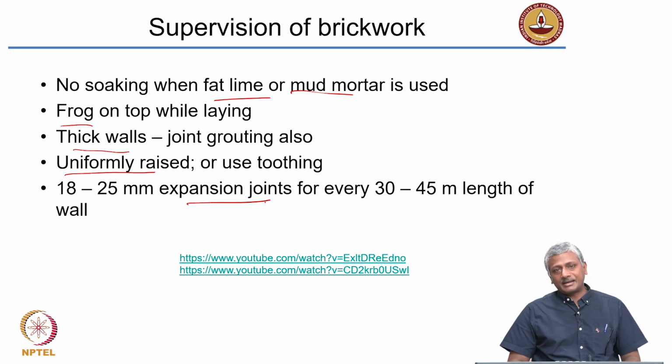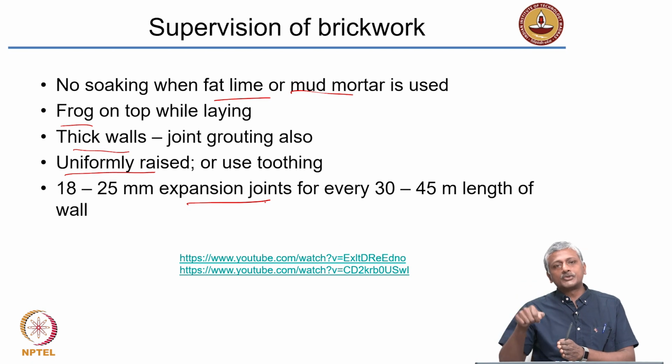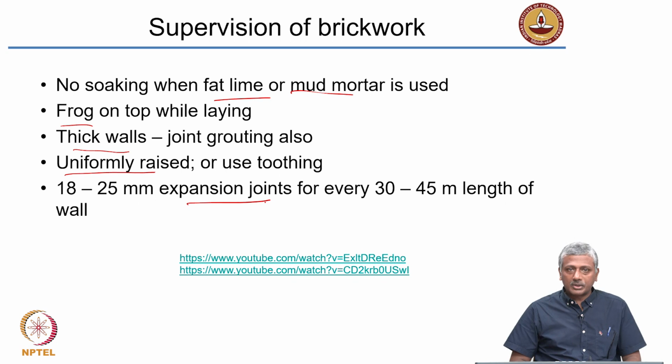So, when you leave behind these joints, obviously you need to fill those up with some sort of a rubbery material to ensure that the water does not come through it. Otherwise, the point of providing a joint is lost.